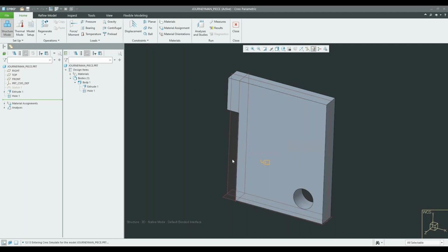So here's my model. And so I want to go in and I will show you what these are. First off, I have a material assignment. So we'll just edit the definition of that material assignment. This little box is going to pop up and I'm going to say more. We have legacy materials. These are the old Mechanica materials, and you can use those. We have fluid materials.